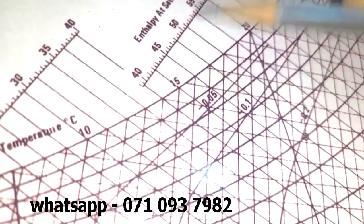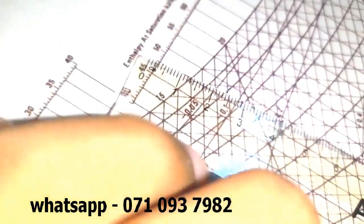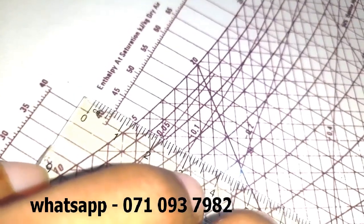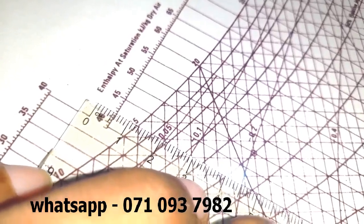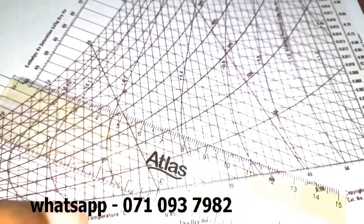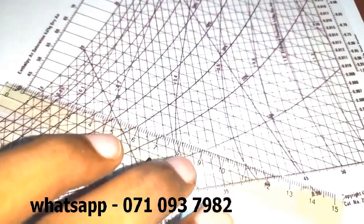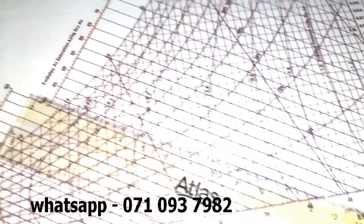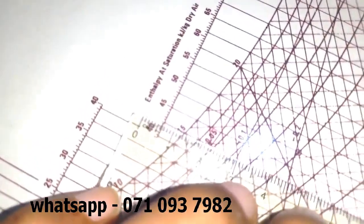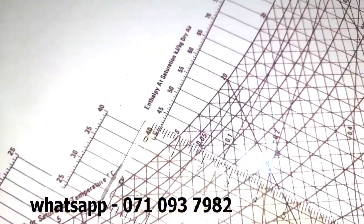Now be very careful. Take the ruler. We know that wet bulb temperature lines go in this direction. You know these lines, I have previously taught you. These lines make an angle with the left horizontal of approximately 25 to 30 degrees. You got it? So now take the ruler. We know the point of intersection, and now we are going to read the dew point temperature. Let's focus again.